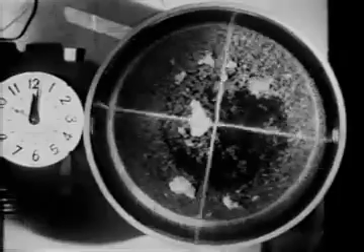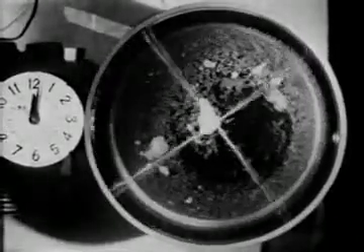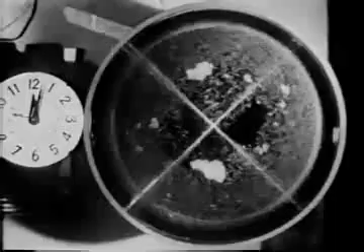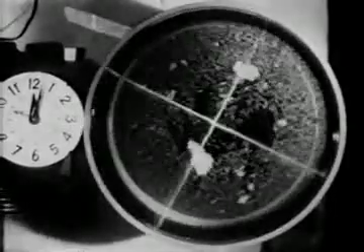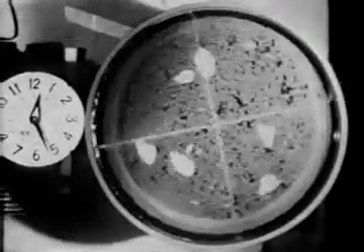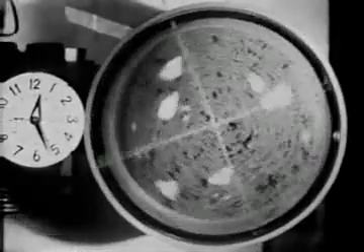These viscous forces gradually diffuse outwards from the wall, and more of the fluid circulates. In the end, viscosity brings all the fluid into a perfect solid body rotation. At this point, paradoxically, the viscous forces have vanished altogether, and there is nothing to force further changes in circulation.